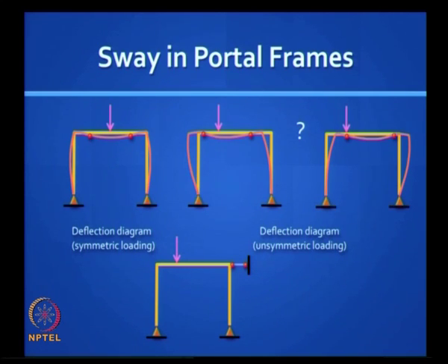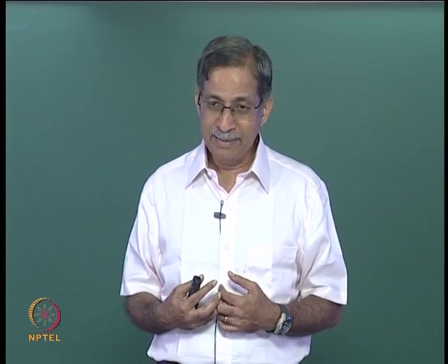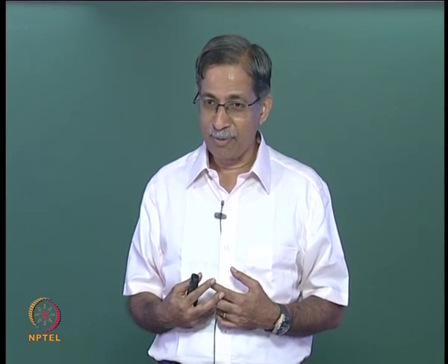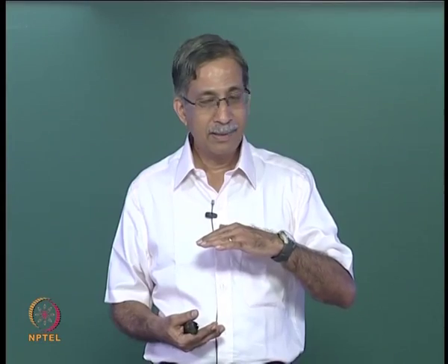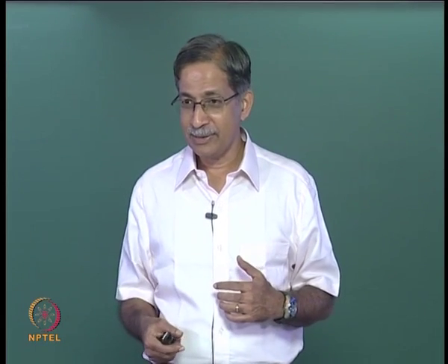Now, will you have a horizontal force at the bottom? Yes. What will be the value of that force? It will be the moment at the top of the column divided by the height of the column. So you will get two horizontal forces; which one will be more, or will they be equal? Why do they have to be equal? And opposite.